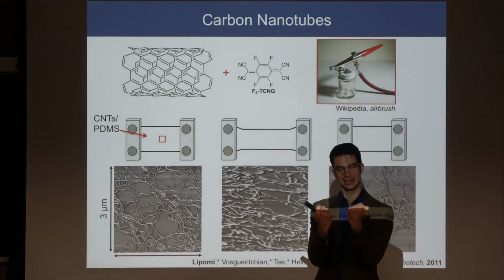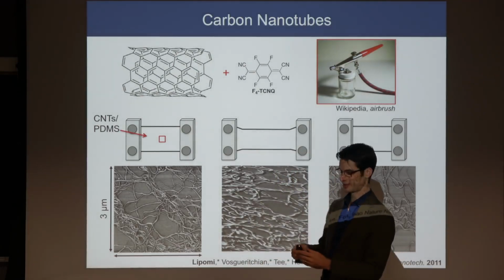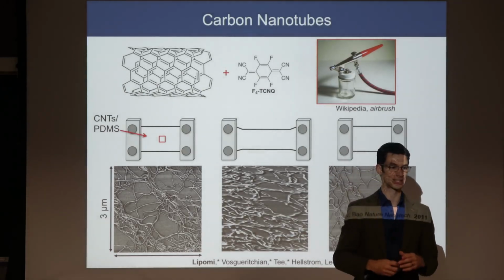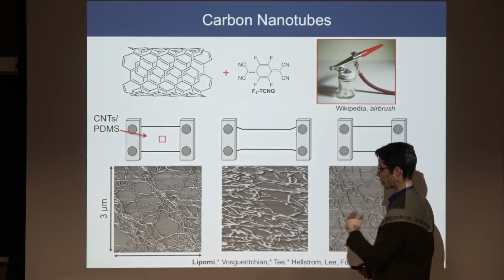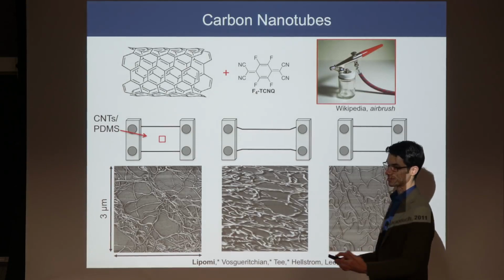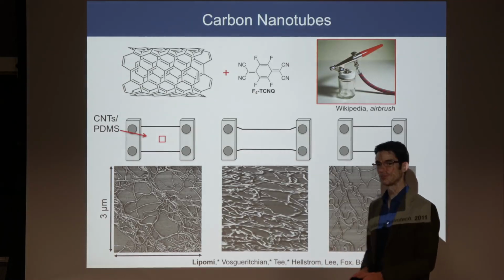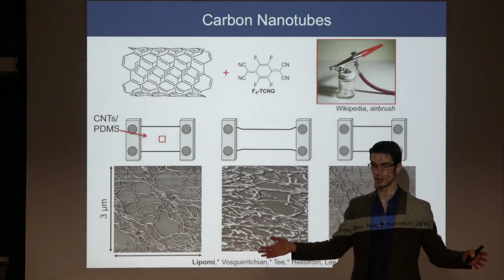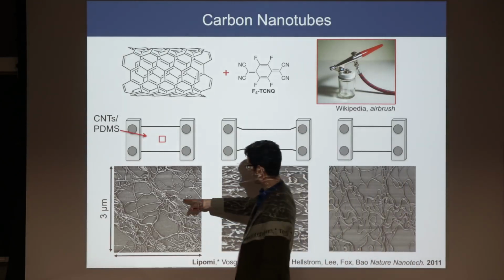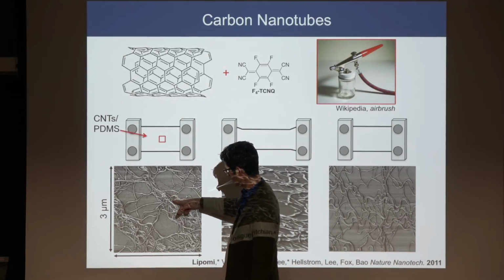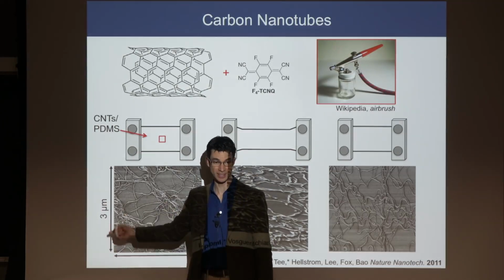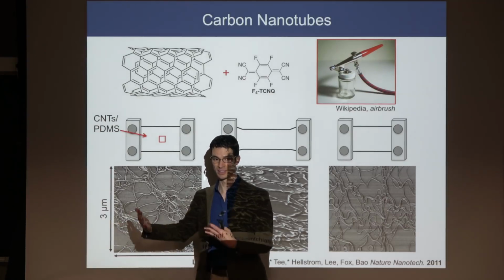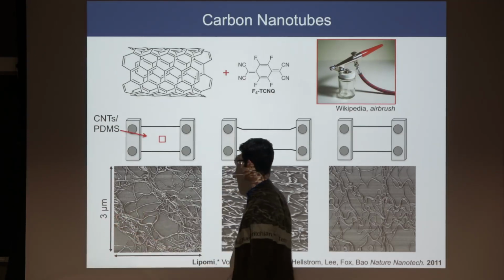And the aligned type of carbon nanotube that has no chirality is a conductor. It's basically like a really thin metal wire, but it's made of carbon. So it's really a statistical argument that says conductive ones are less. Nevertheless, if you have some randomly deposited carbon nanotubes that bundle up into these bundles, the whole network is conductive because there are enough conductive ones to supply conductivity to the entire film.